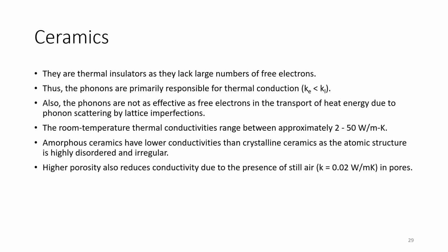The amorphous ceramics have lower conductivities than crystalline ceramics as the atomic structure is highly disordered and irregular. The higher porosity also reduces conductivity due to the presence of still air, which has a conductivity of 0.02 watt per meter Kelvin, and this air is found in pores in the case of ceramics.